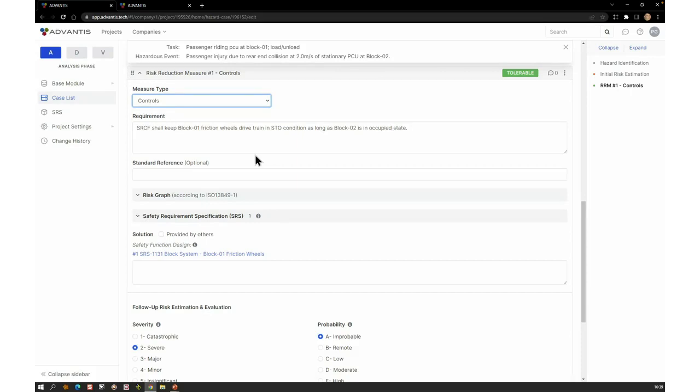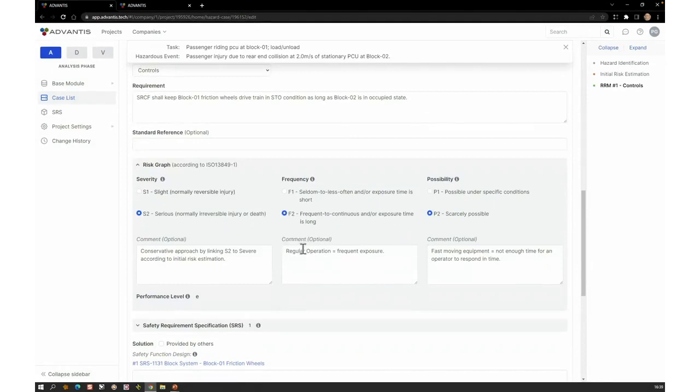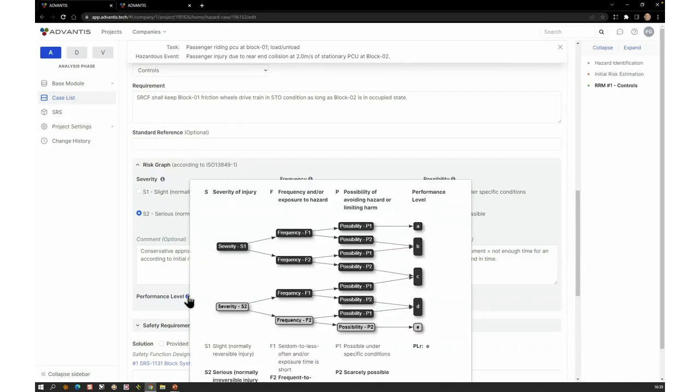So now, that's given by the standard, whether it's the risk graph or a risk matrix. If you choose to go with the IEC, you can select at the beginning of the project which route you want to go, whether it's ISO 13849 or IEC 62061. 90% of the customers pick this one here. So then we have this loaded, looks like this. You've got the 3 parameters for the ones doing control system design.